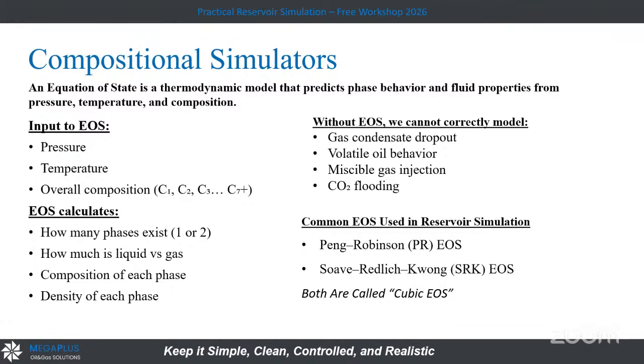It will dissolve in the oil. That's why it's called miscible, and otherwise it will never dissolve. If the oil content is measured, it will be C5, C6 and C7. So in that case we need a compositional reservoir simulator, so we can simulate the miscibility of the carbon dioxide or lean gas in the light oil, and the change in the viscosity of the oil, and then it will come out and be produced.